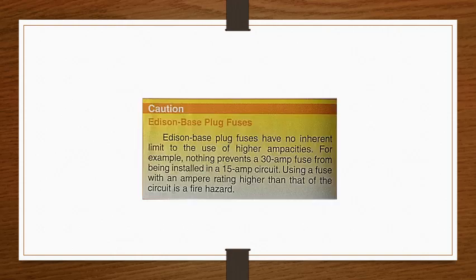Caution: the Edison-based plug fuses. The Edison-based plug fuses have no inherent limit to the use of higher ampacities. For example, nothing prevents a 30 amp fuse from being installed in a 50 amp circuit. Using a fuse with an ampere rating higher than that of the circuit is a fire hazard.